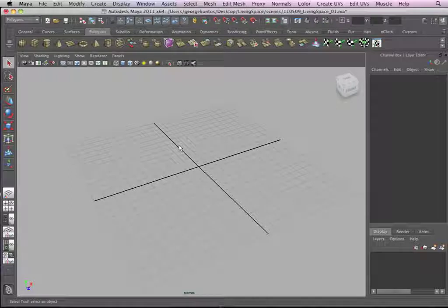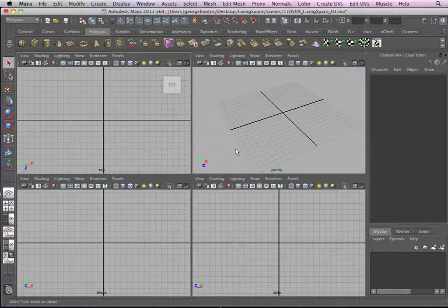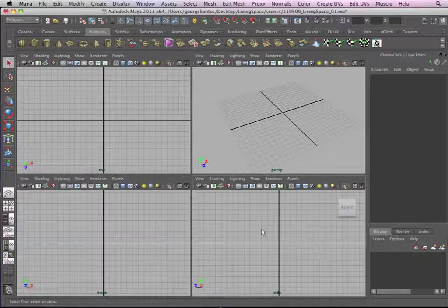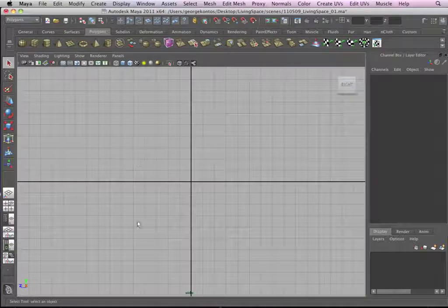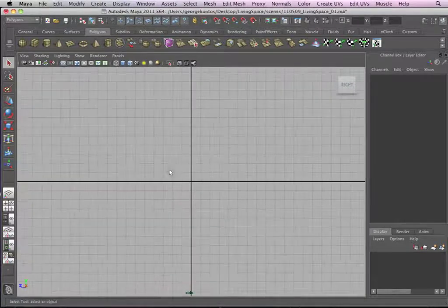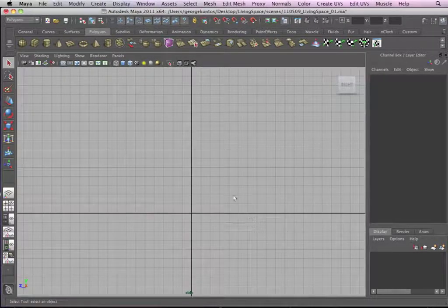It makes it much more complicated to open doors and open holes on a cube because you have to open two holes. Whereas if you have only one flat plane, you can open one hole and you're done. That's a nice fast workflow. So I'm going to tap on the spacebar, go on the side view, click on the side view, tap on the spacebar so I can maximize the side view and work on an orthographic view, which is easier.